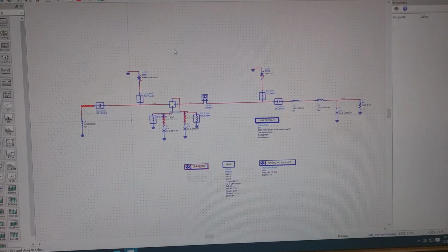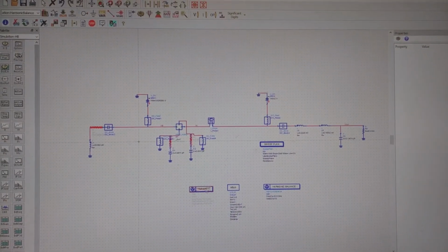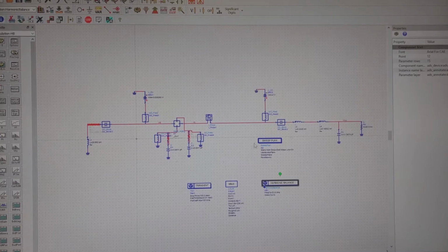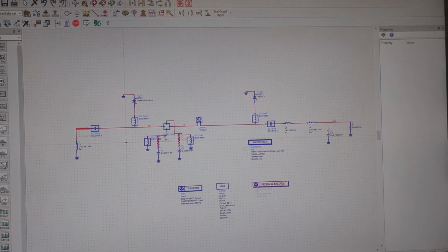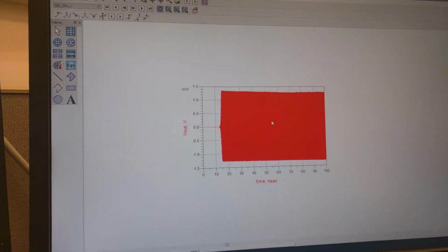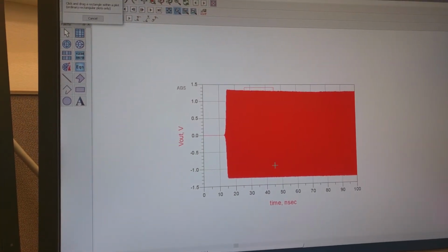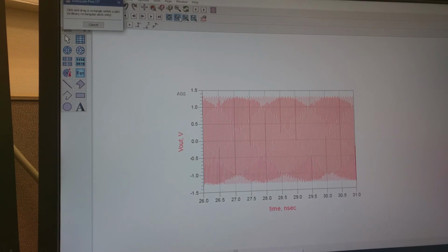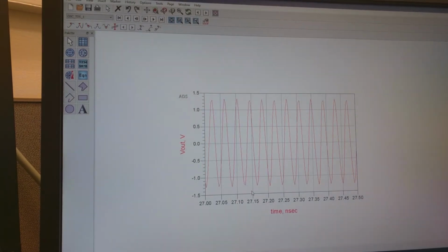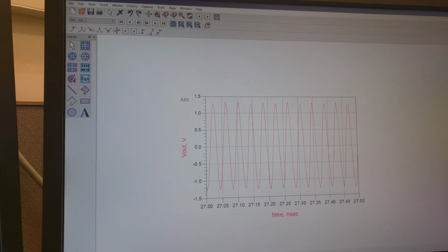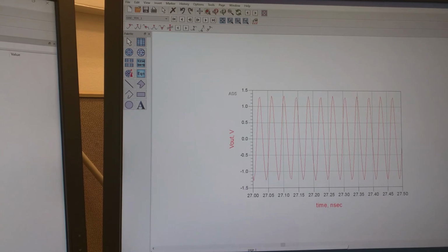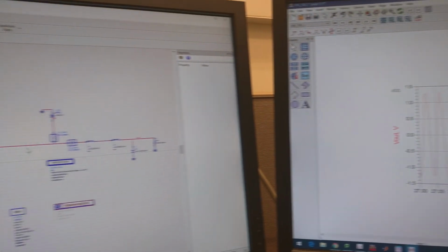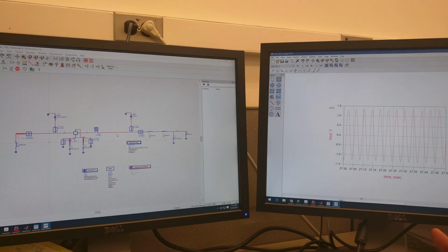Now I'm going to run a transient simulation. You bring in the transient block, you remove the harmonic balance block, and you run the simulation. And you plot V out, and boom. You see that this is now oscillating, with a frequency of 25.08 gigahertz. Once this is oscillating, you can go to further steps and tune this and bring the frequency to your design frequency. Okay, that's it. These are the steps of designing this oscillator. Thank you.